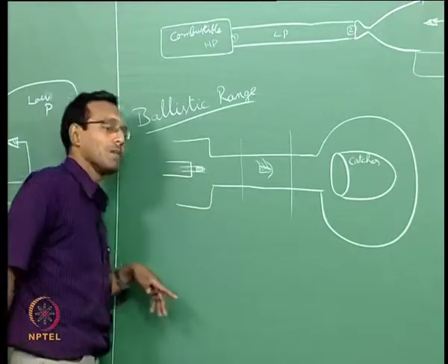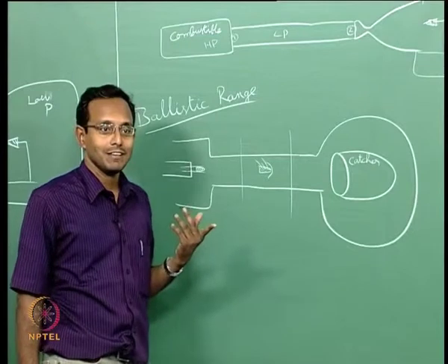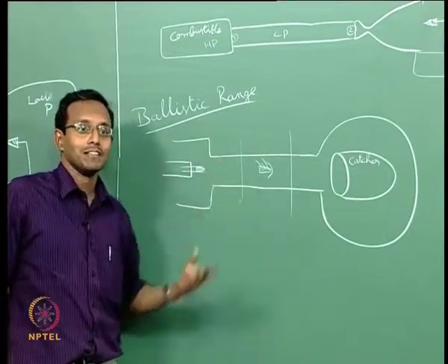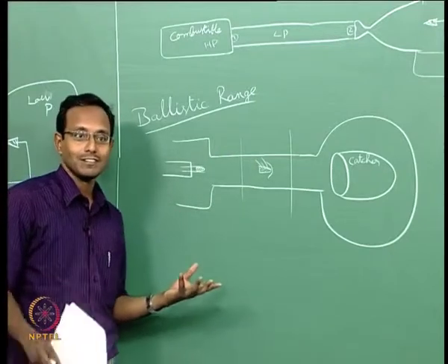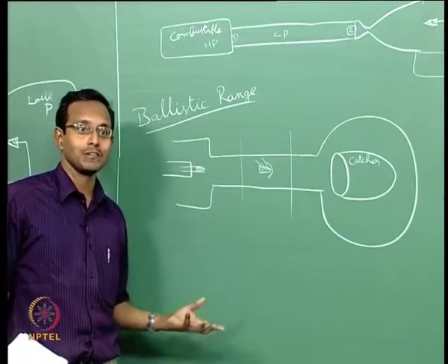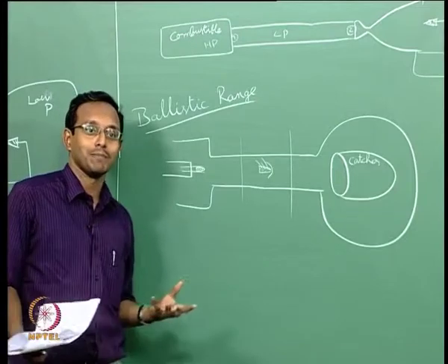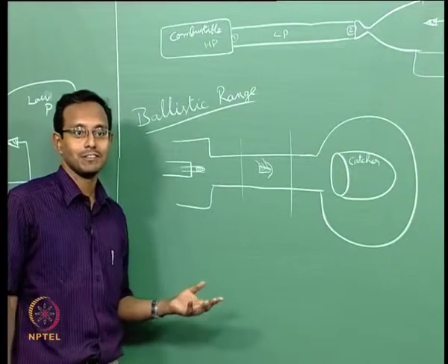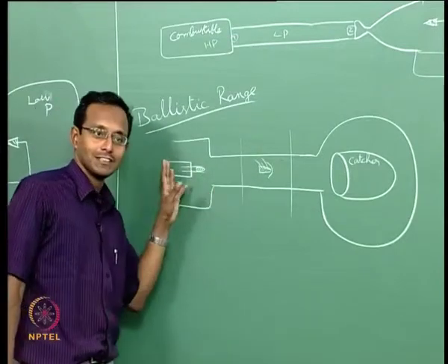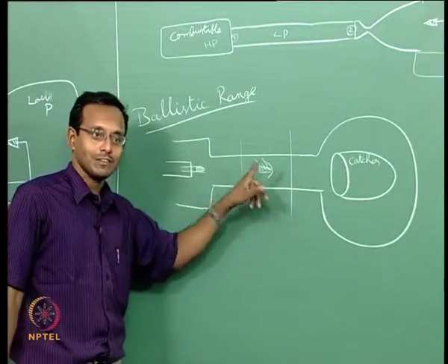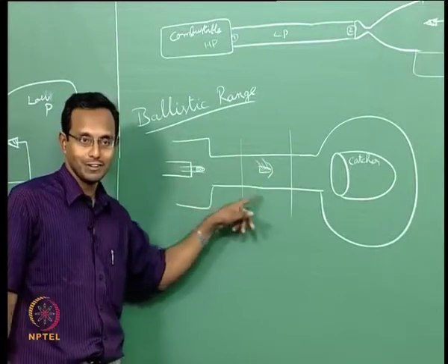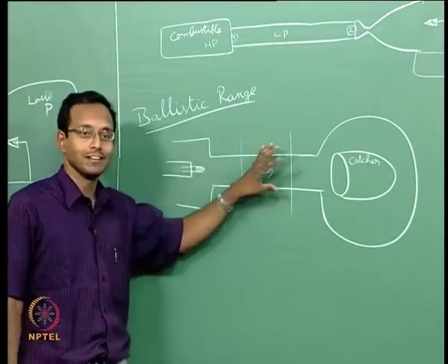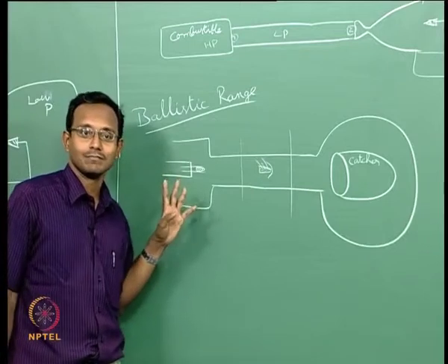Okay. The problem with our regular supersonic tunnels is, when we work with our kind of P0 and T0, when we go to say Mach 3, the pressures in the test section are not regular atmospheric pressure conditions, they are lower. They are probably like 0.1, 0.3, 0.5 kind of bar values, 0.5 atmospheres, 0.2 atmospheres, that kind of pressures. Okay. But in these facilities, I can maintain it to be atmospheric pressure, already existing air around in here, and just shoot this bullet. As long as the flow is very stagnant in here, my experiment will be clean.